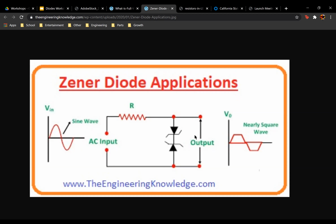So that's why it's called a diode protection circuit, because as you can see at the output, if we put our load there, that load is only going to receive a maximum of 8.6 volts. And that's why it's getting clamped off right there. That's one of the applications of a Zener diode, and that's why it's important, because it helps us prevent our load from frying.